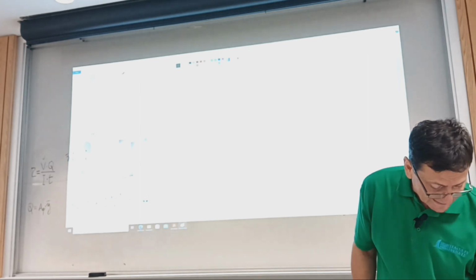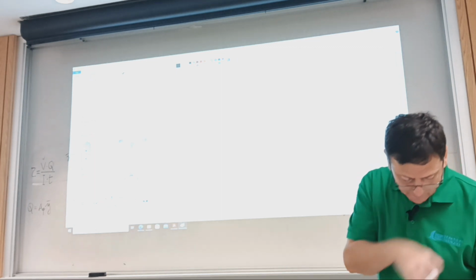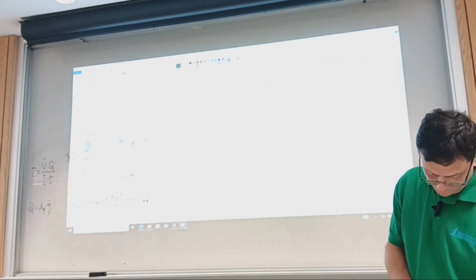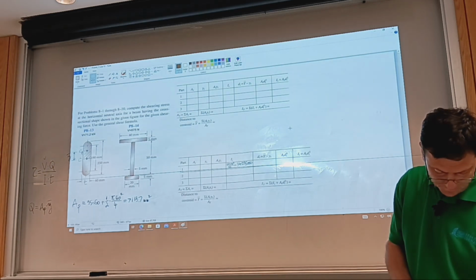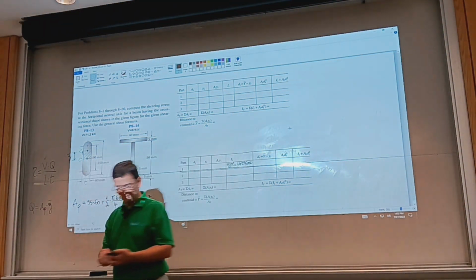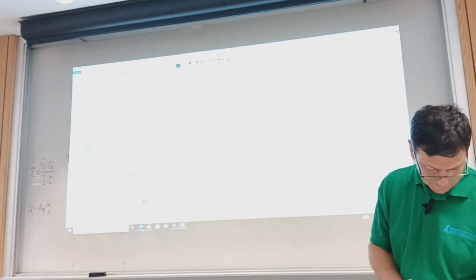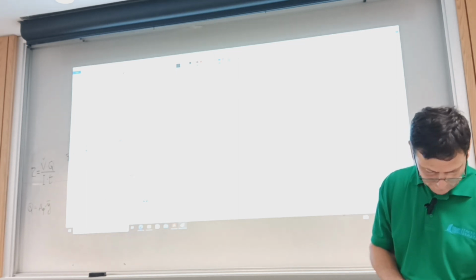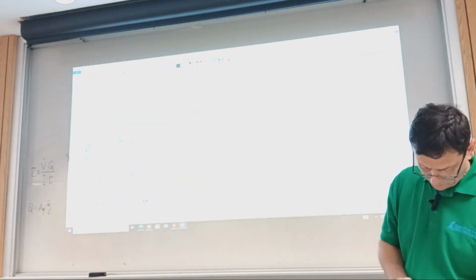On page 754, we're interested in Ix, the centroidal moment of inertia for the half disk. So this is 0.00686 times the diameter of the disk, which is 60, to the power 4.